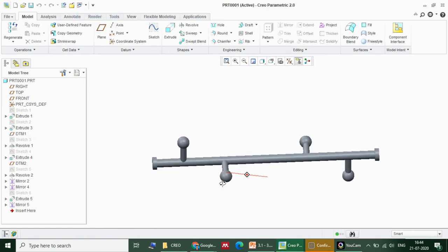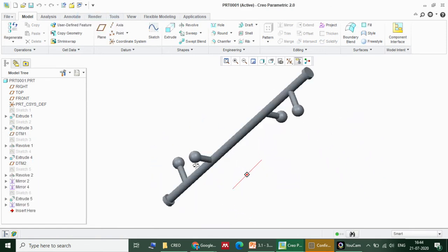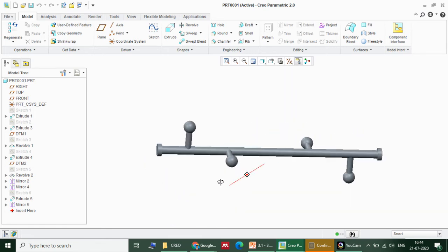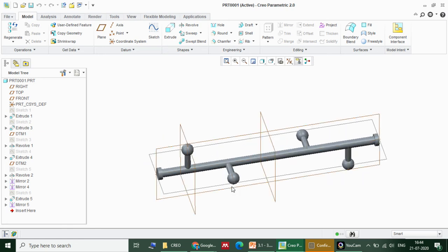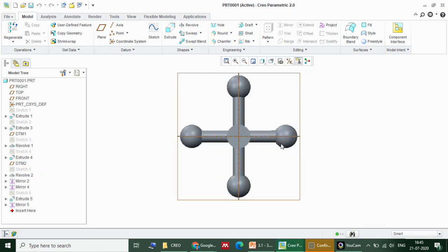If you have masses in multiple planes, different places, far away from each other, then this system requires dynamic balancing. That is the major difference between static and dynamic balancing. In the problems, wherever you go, the given data, some problems may give you the inclination between each mass.